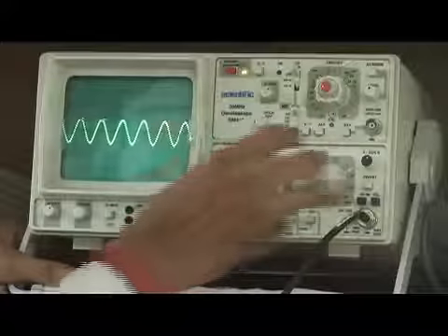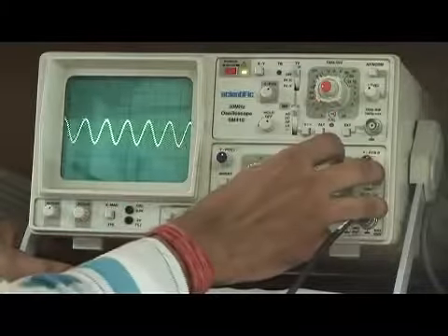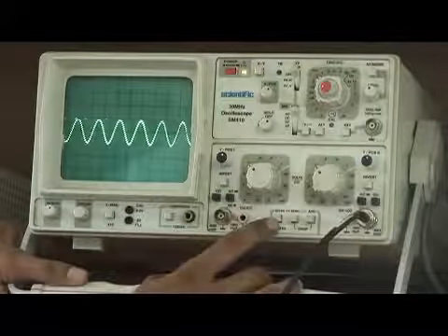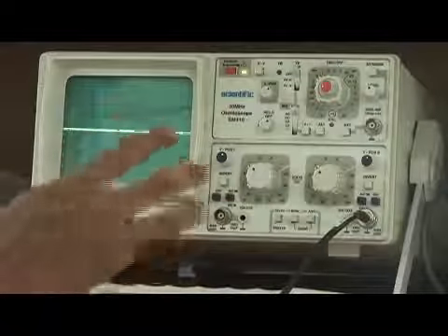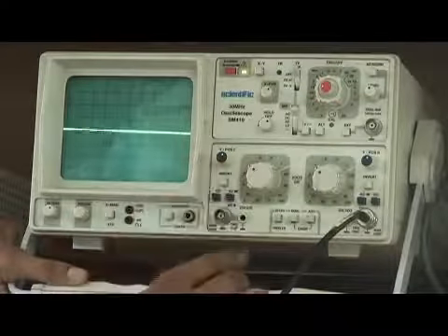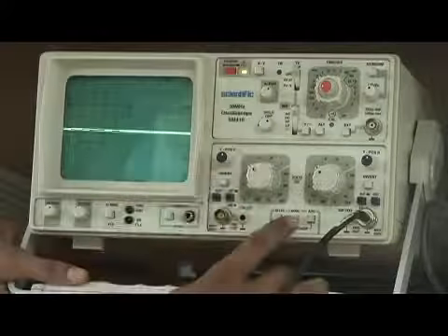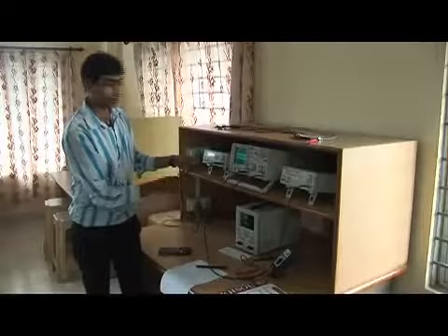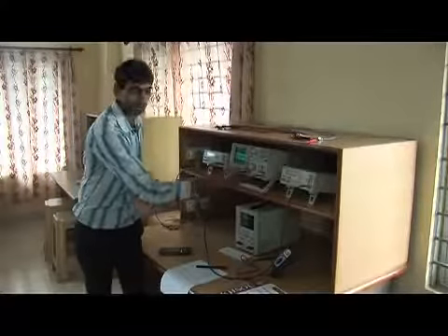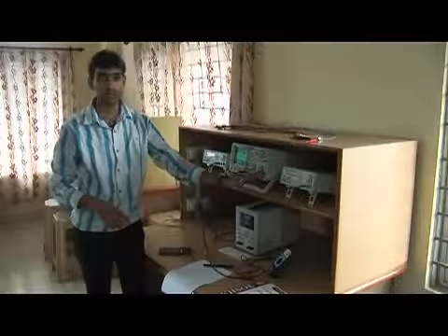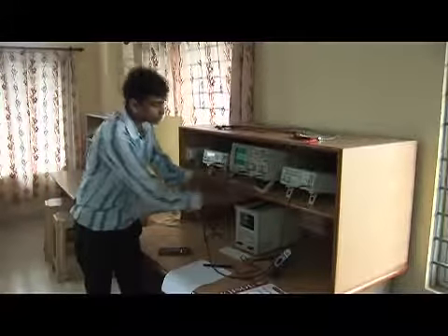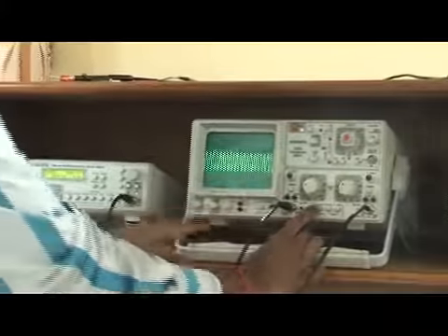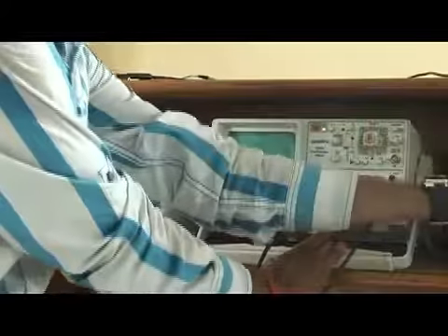So you have 2 channels. The amplitude view for the 2 channels is different, but the frequency view is common for both channels. Okay, so this is channel 2, now it is shown here, and this is channel 1 if you are giving this input here. If you want to see both the channel inputs, suppose I am using one more function generator. I have connected it to channel 1, and the other function generator I have connected to channel 2. When it is in channel 1, you are viewing the signal generated from here, and when we make it channel 2, this signal is being generated by this.